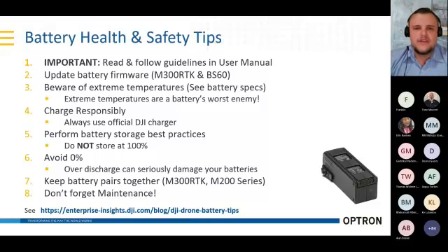And then also with the M300 RTK and the M200 series, you need 2 batteries per flight into the drone. So it's best to keep them in pairs so that you use the same pairs all the time.